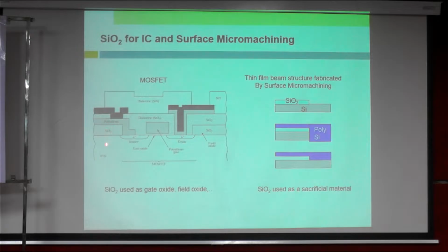You want to isolate it from, or have a structural interconnect with, something. So here you do not want it to connect with some other parts. So you have a dielectric, SiN, silicon nitride. Then you have aluminium. These are things that you need to deposit basically.